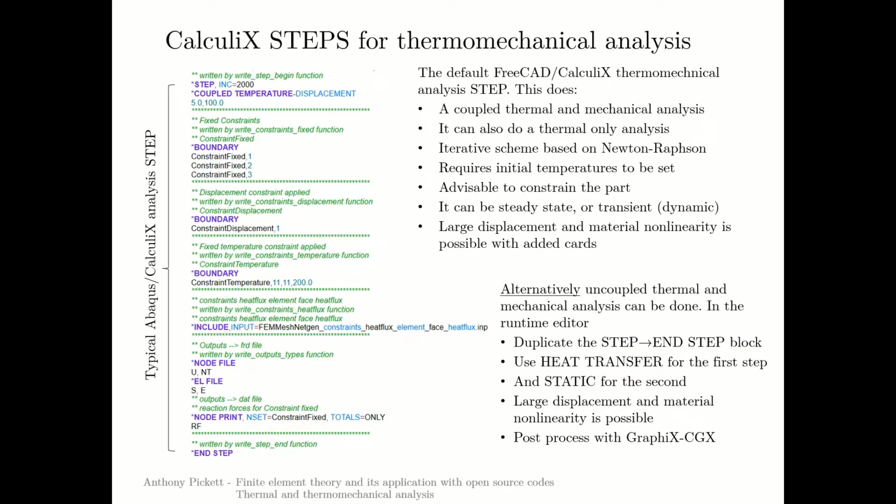I mentioned at the beginning that for a thermomechanical analysis, first of all, you do a thermal analysis, you determine the temperature distribution, and these temperatures are fed through to a second analysis, which is a mechanical analysis, which converts these temperatures into strains, thermal strains, which are then converted in effect to nodal forces, added to any additional applied forces, and the mechanical analysis is performed.